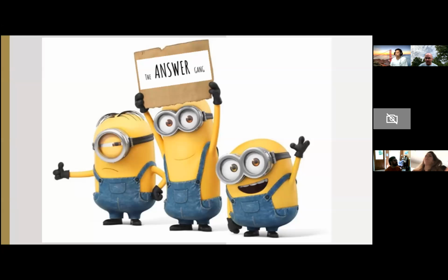So for the Quadra, yes, we're gonna have a leg down, because we don't want the daylight opening surface facing the clamp or the bed, so we won't get scratches. For the DMI, Satellite and Planet, we can stand up the part, so we can get 3 sides fabricated. For the stack joint, it all depends how complicated the part is. But once we set up the orientation, we will not change. Right now, we will have all the glass pockets facing down.